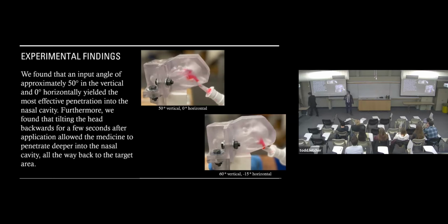And then in case you noticed on our measuring setup, there's possibilities for hundreds of different tests with just varying degrees and possibilities. So one of our main design concepts with this model was the ease to take it apart and run tests as fast as possible. So 4 nuts, zip them off, 3 pieces come apart, and then for each test, all it takes is to dip it in a little water bath, dip it in an alcohol bath, and we found that the leftover dye comes right out of it, and we were able to perform tests every couple minutes or so.